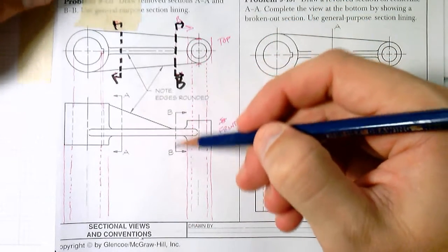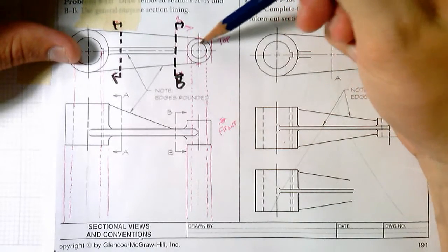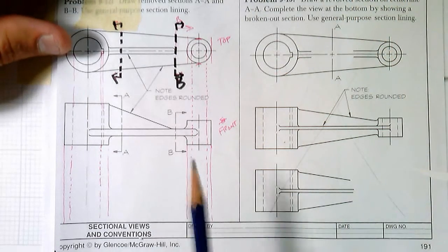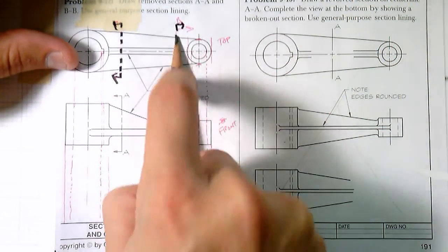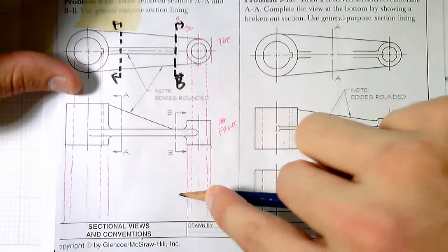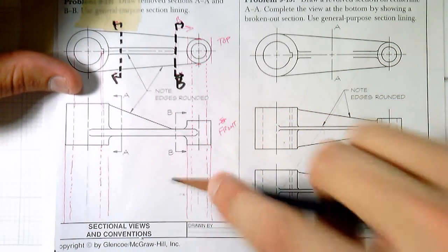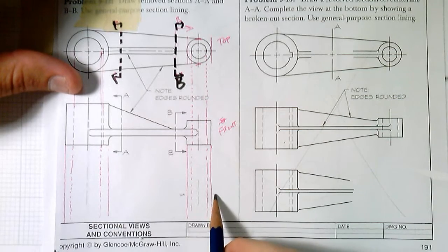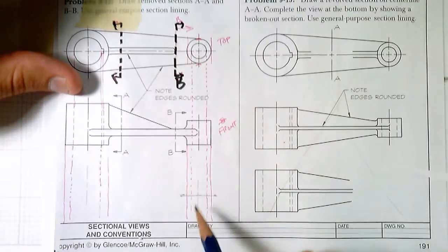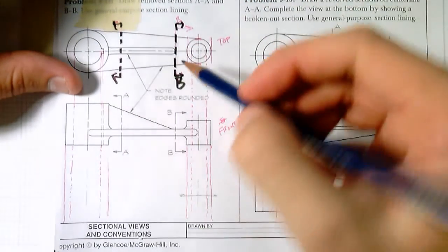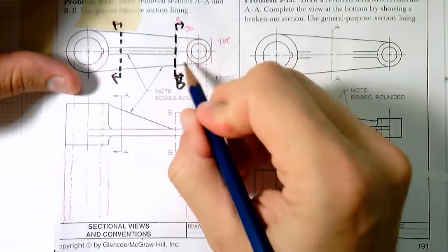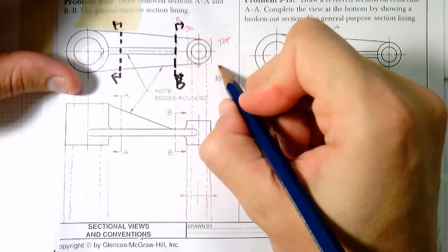When you cut through the side view or this top view, you're looking at the cylinder from the face over here. So the first thing we're going to do is take the information of how wide that face is, and here it's about the width of my pencil. I'm going to place that horizontally, and that placement is going to look something like that. It's going to be that kind of a length, because that length and this length are the same. Just to clarify, the section is going to look like this. It's going to be one cutout, which is that material, and then you're going to see the cylinder behind it.